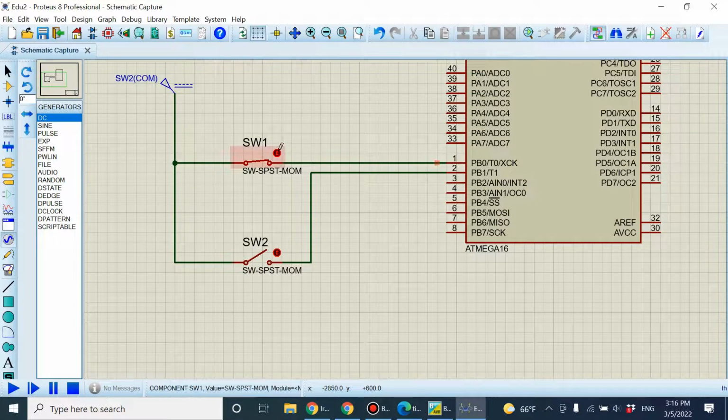So when I just release the key, it's not here anymore. Okay, so this pin should be high Z. High Z means it's not connected to anything, but the microcontroller pin will remember its last state, and it sends 1 even if the switch is not connected. Okay, what should we do then?